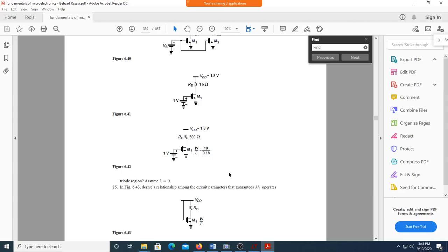Of course, for this particular problem, to answer your question, not entering the linear region with minimum voltage is exactly equal to not entering the saturation region with maximum VDD. Yes, because when you are at the verge, it is the minimum for your saturation and the maximum for linear. You'll always look for minimum voltage in case of saturation voltage.